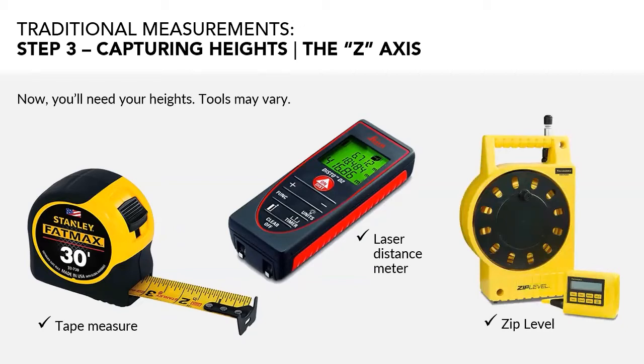This is an excellent tool that we've been using for many years. It's invented, distributed, and repaired if needed by a company out of San Diego. I'm actually not aware of any other version of this tool, but it basically uses displacement to read heights anywhere within a 50-foot radius. So this is super helpful when you're measuring over large spans of distance.